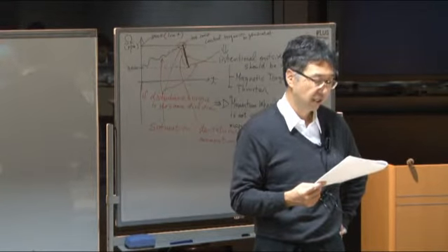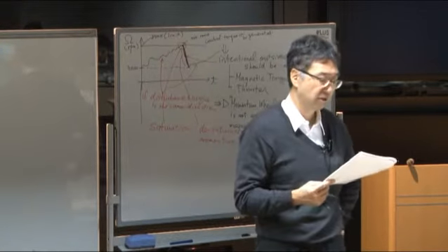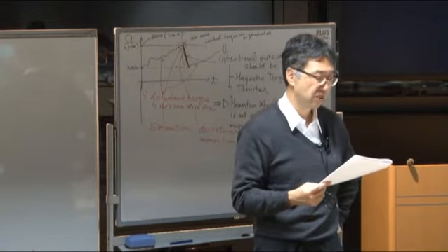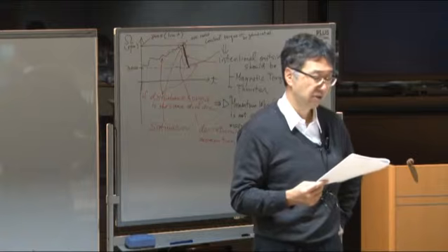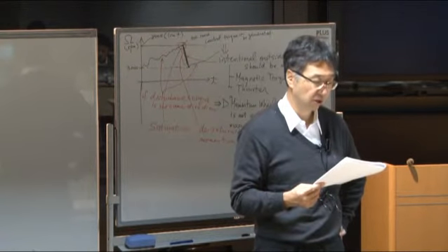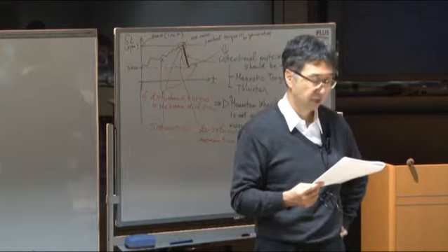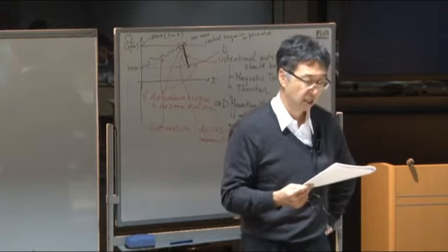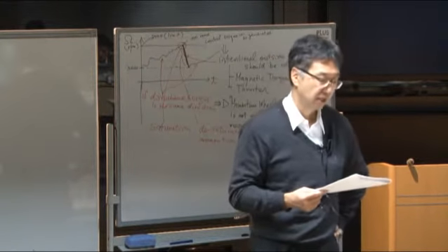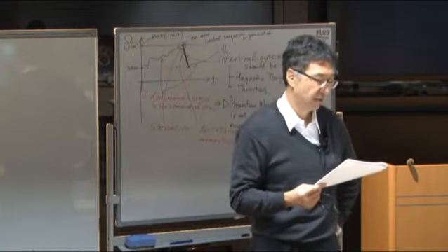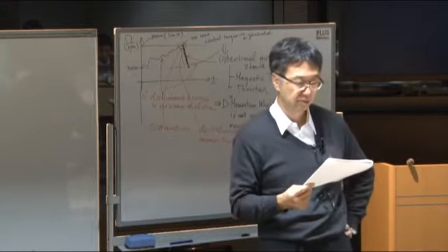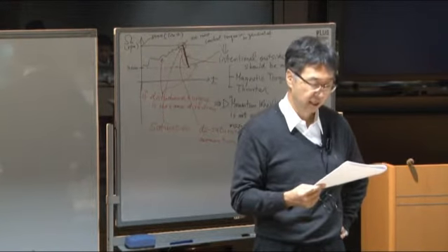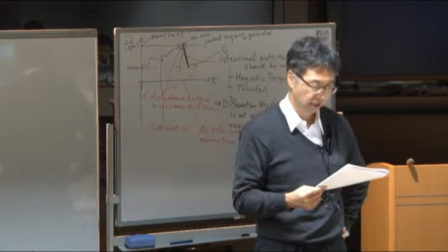But from Intelsat 4, it became a dual spin satellite. Maybe you can have a small gap at the center of this long cylinder that separates the platform and rotor. And as I said in my lecture, this kind of long cylinder is possible in this dual spin satellite. And Intelsat 5 is a 3-axis stabilization. This is a bias momentum satellite. And Intelsat 6, again, became a dual spin satellite.